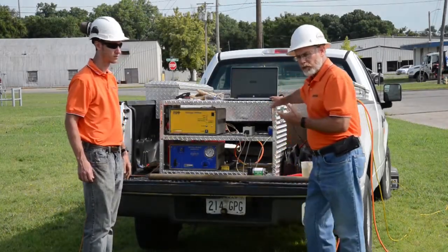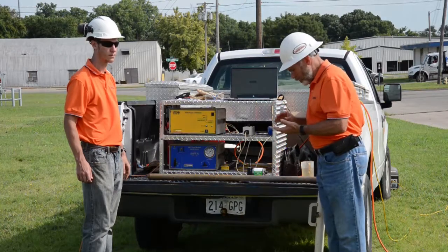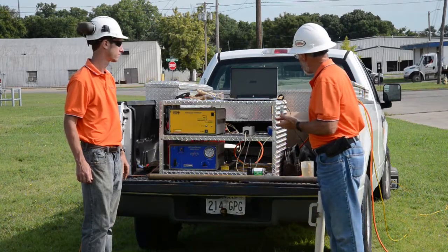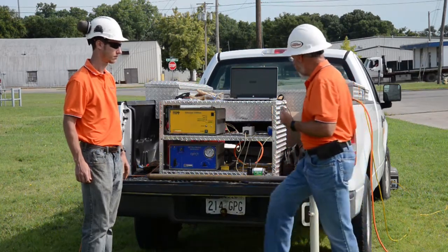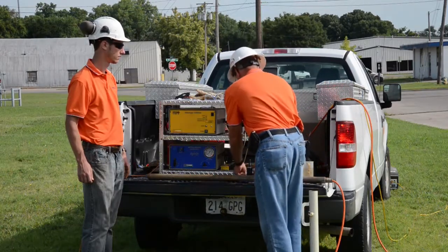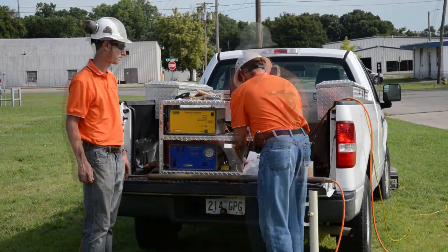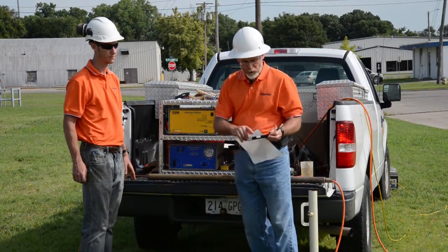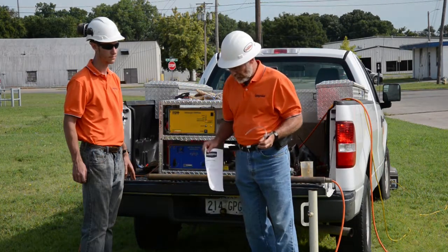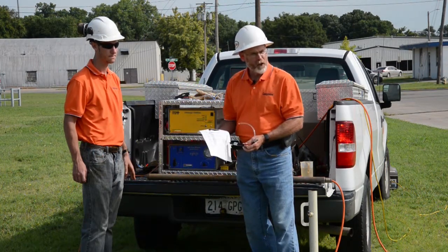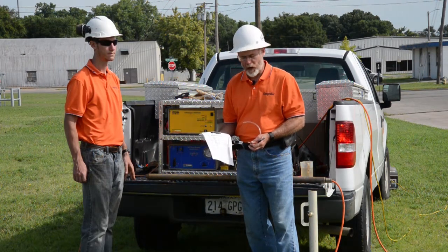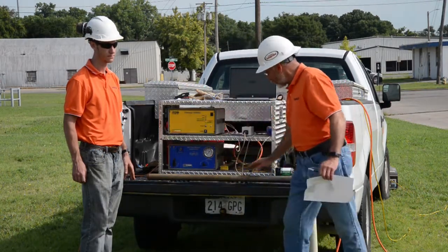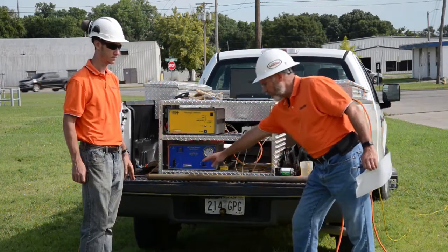In the software here, it allows us to choose the tool, the probe we're running. This is a KS6050 HPT probe. It also will allow us to enter calibration for our HPT transducer. So this HPT transducer is our pressure transducer, and each pressure transducer has a serial number and a calibration sheet that gives you the calibration curve and the data to enter into the software when you install a new pressure transducer. And the pressure transducer sits in the connection tube here just above the probe.